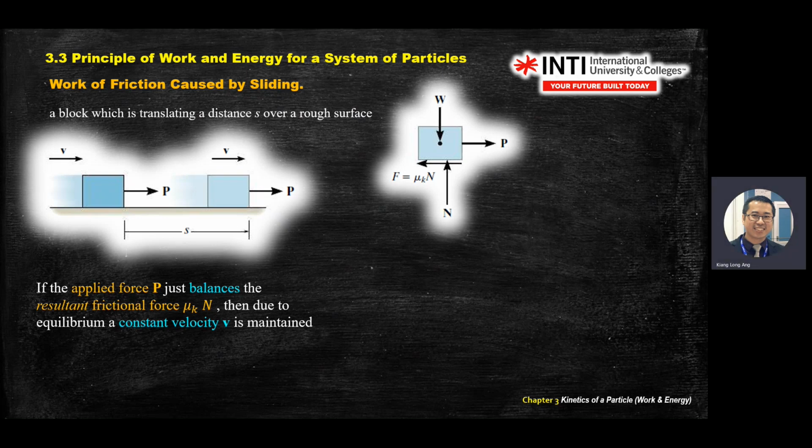So start practicing when you draw free body diagrams, start to put in the center point for the object from today onwards. Previously we didn't want you to fit too much information, but now, starting today, you already learned and you're able to understand. So start to have a dot for all your free body diagrams, which is your CG point.